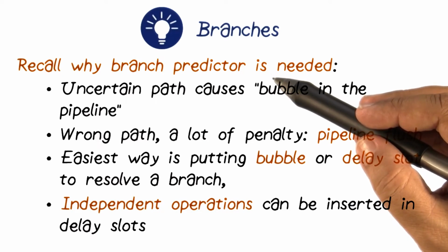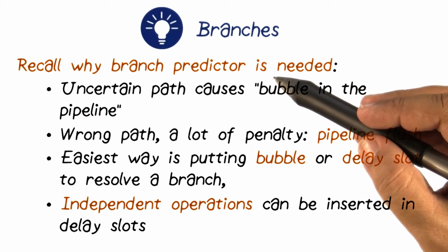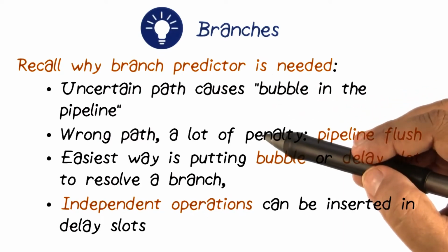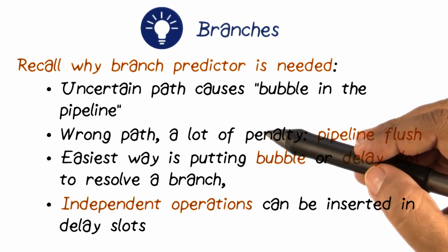Alternative is to be able to move branches up in the control flow and fill the idling slot with instructions that would definitely execute regardless of the branch outcome. This is a preferred solution for embedded systems, and it does not need extra hardware, and it also uses those branch or delay slots by carrying out some useful operations.